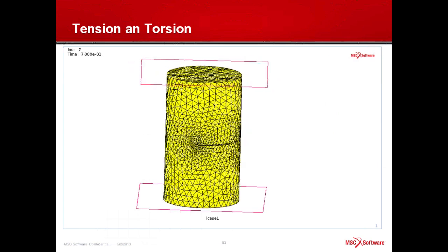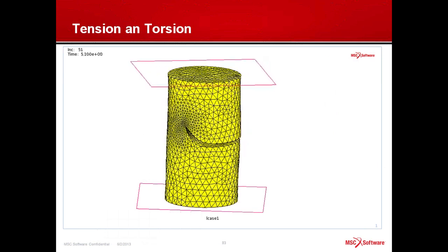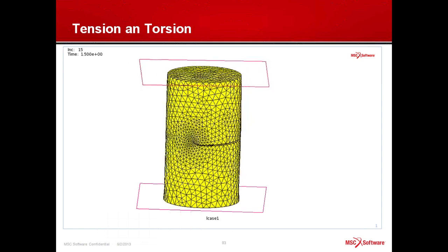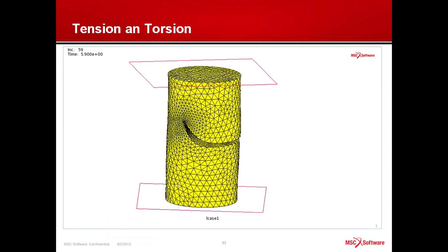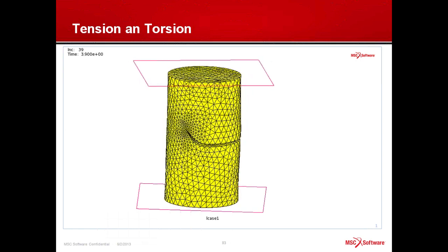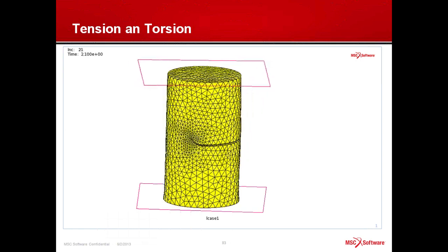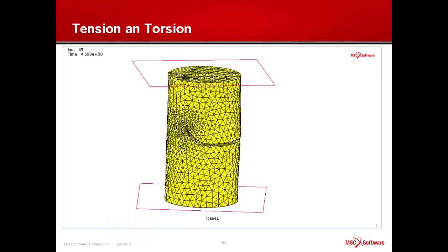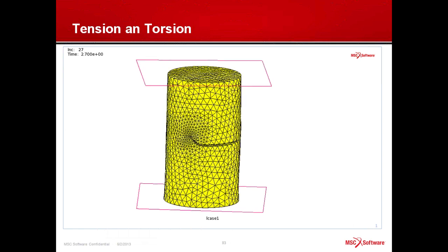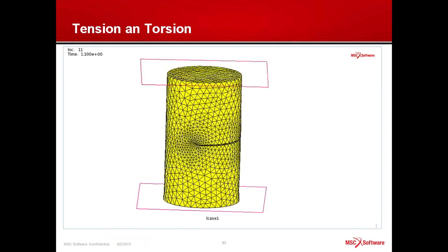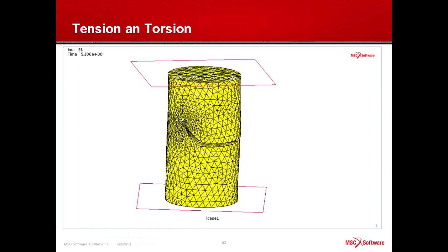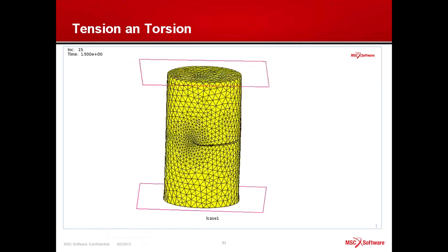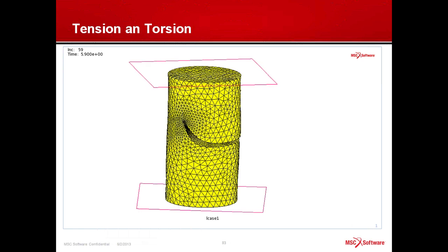Or you can look at the forces on the bodies, and again the force is reduced after the bodies crack. And this occurs with, we see whenever we do adaptive meshing, we're using tetrahedral elements. We can either use the simple tetrahedral elements if this is elastic material, or we'd be using element type 157 if this was an elastic plastic material or a rubber material. The fracture mechanics capabilities are available for any material model.